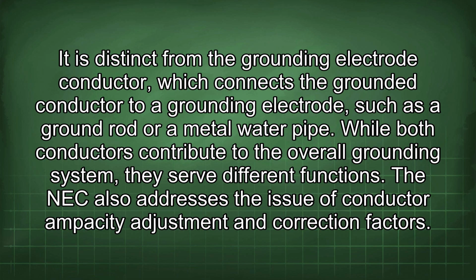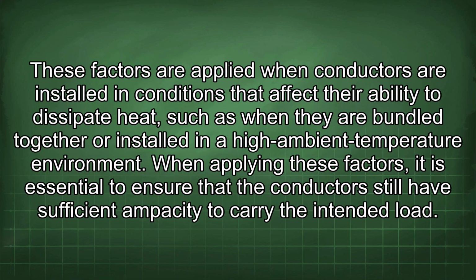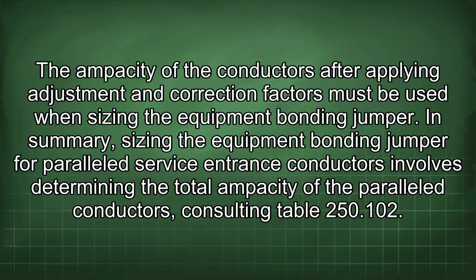The NEC also addresses the issue of conductor ampacity adjustment and correction factors. These factors are applied when conductors are installed in conditions that affect their ability to dissipate heat, such as when they are bundled together or installed in a high ambient temperature environment. When applying these factors, it is essential to ensure that the conductors still have sufficient ampacity to carry the intended load.